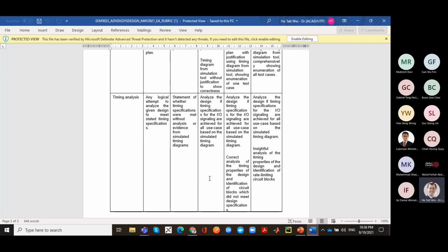That's a really, really good example. You have to wait a specific duration of time, not a specific number of clock cycles, right? It's a specific duration of time, because the circuit you're interfacing with has this kind of time limitation, there's a certain delay. So this timing analysis part is actually checking to see, did you pay attention to the specification of the problem, to the requirements? Is there any specification in terms of time, and how do you relate the specification in terms of time to your system clock, right?